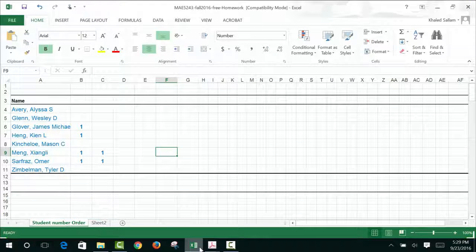6.02 is wrong. What's R for air, the gas constant? 8.31 is wrong. I wanted it in joule per kilogram Kelvin. Does anyone remember the gas constant for air? 287? 287, that's correct. Who said that? Omar.